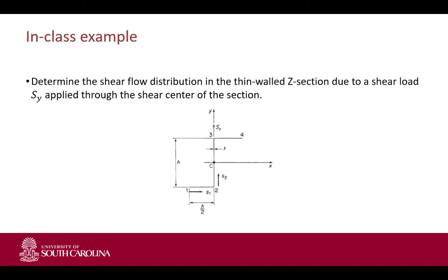Yeah, let's do a small example. Determine the shear flow distribution of this thin wall Z section due to shear load SY applied through the shear center. The concept of shear center is very important, but we'll get to that in the next lecture. So let's quickly draw that up.